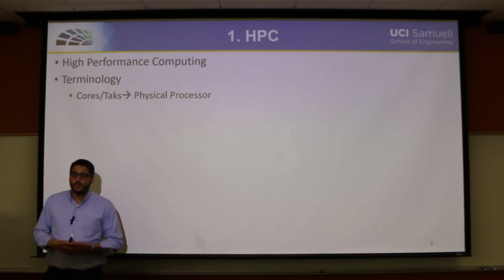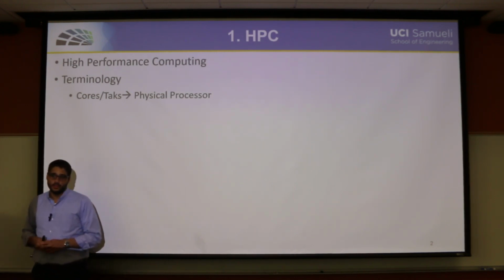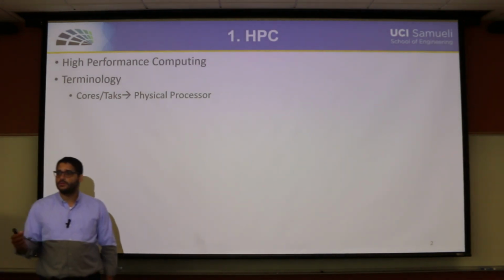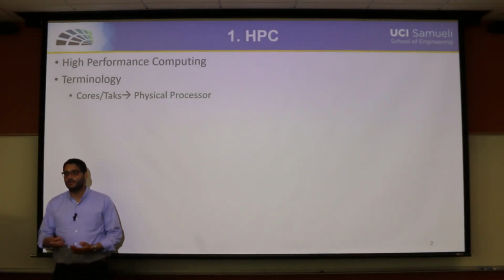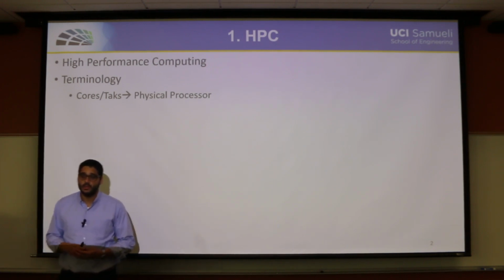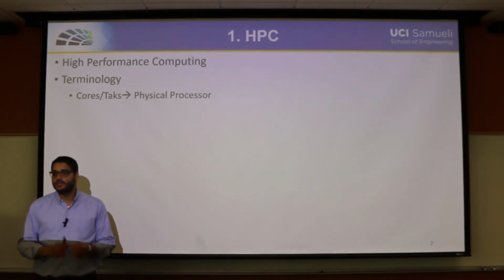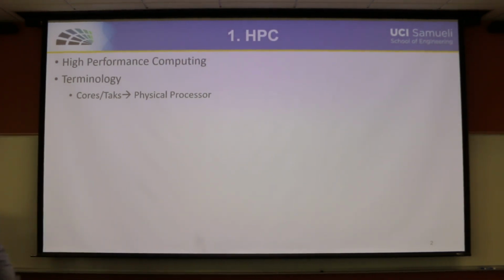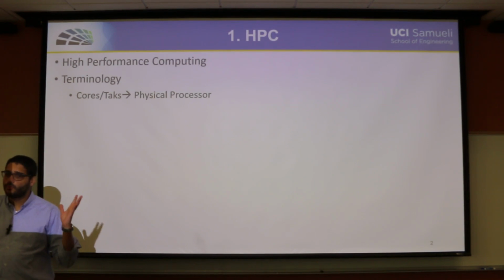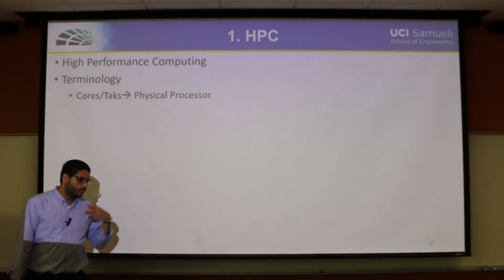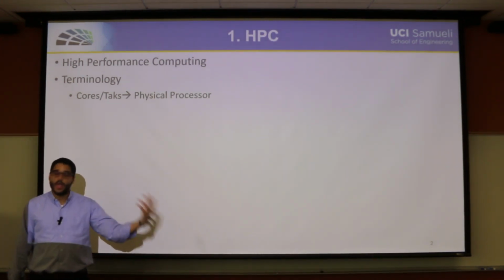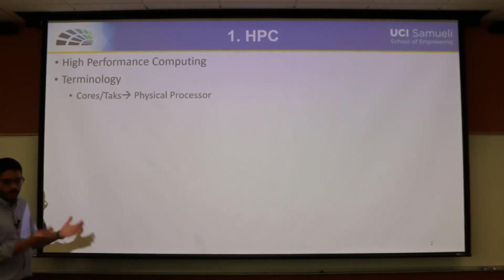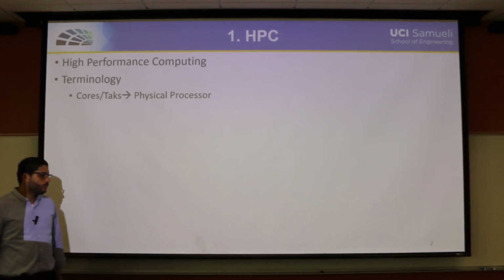However, Fluent does not use hyperthreading, and if hyperthreading is allowed from your BIOS, it's encouraged to be deactivated, because Fluent deals with the exact number of physical cores. In most HPC, hyperthreading is not allowed, so the number of cores that you ask for in your job is exactly the number of processors that you will be executing your Fluent process with.